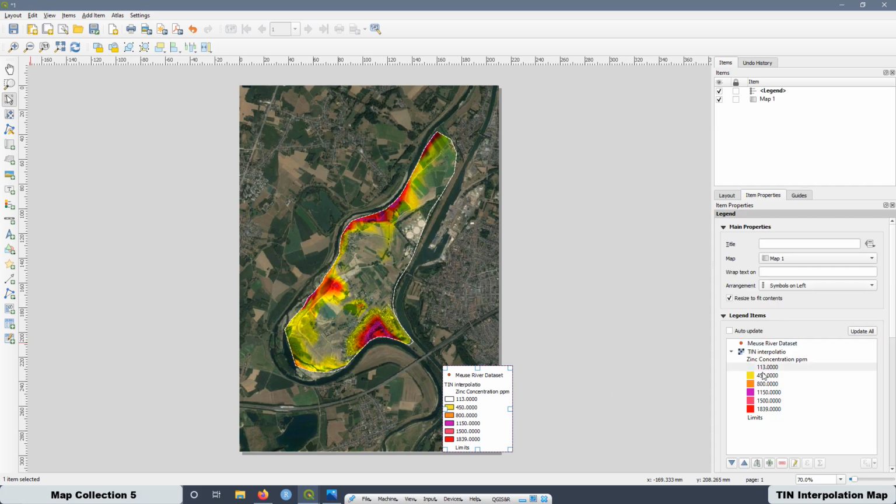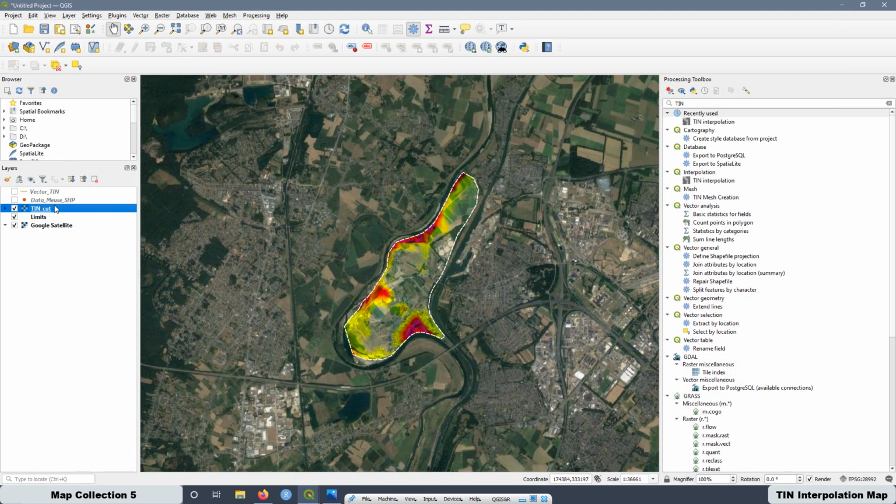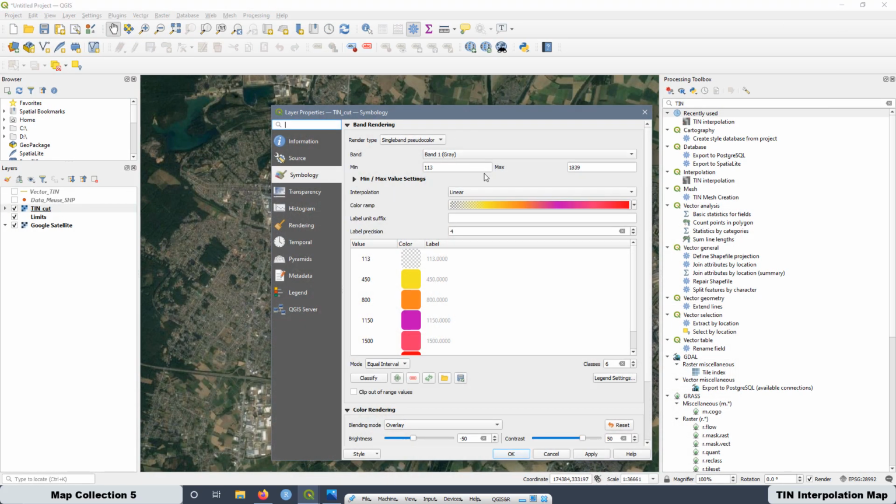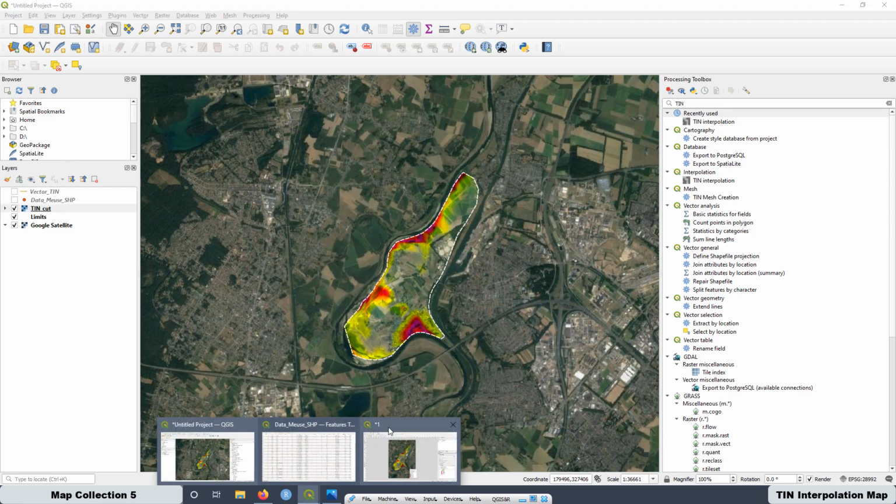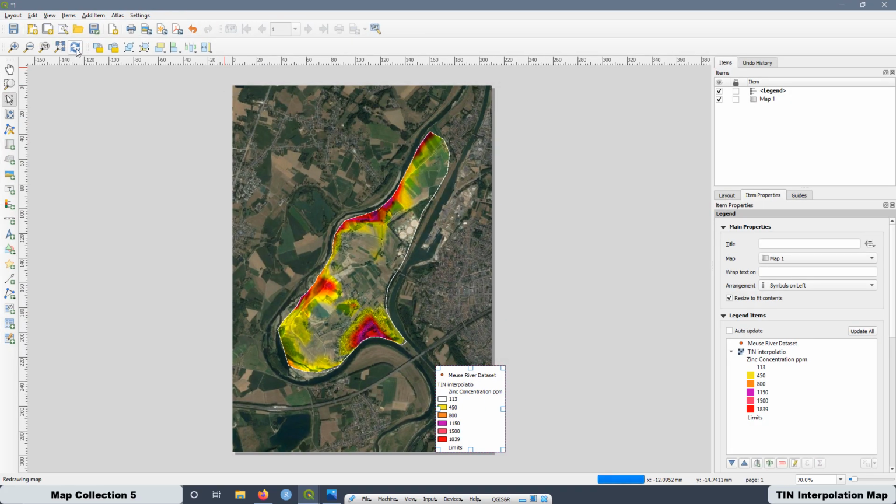Now let's work on the formatting of the numbers. But first I would like to remove all the decimals, all these zeros that I don't like. Then go here to team interpolation. Then here we are going to add 0 because we don't want any decimal. And apply. Okay, now we can go here, refresh this page, and now we have no decimals here.